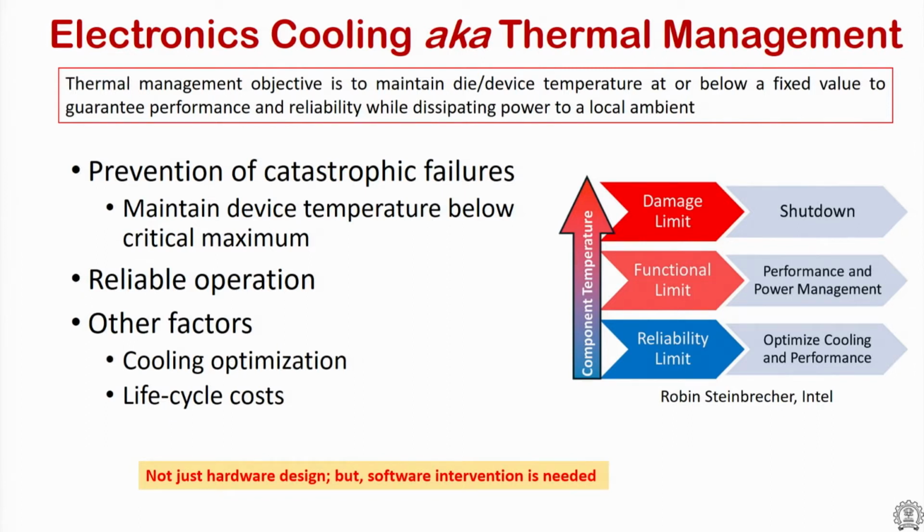and these processors these days have thermal sensors in them that continuously monitor the temperature of the devices. Let's say, for example, the sensor is set at 100 degrees C. If the temperature sensor reads 100 degrees C, the system or the microprocessor automatically shuts down by itself.